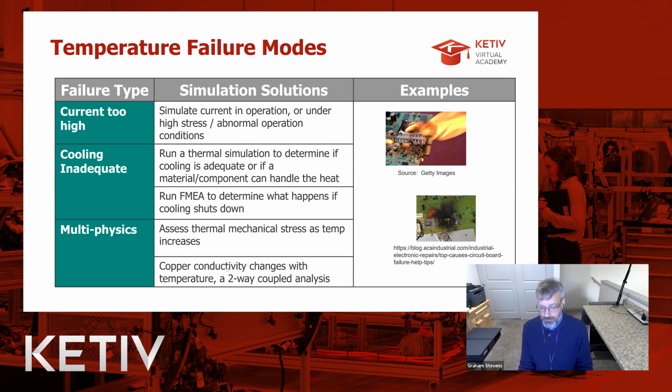And then there may also be some multi-physics simulations that might be useful in this situation, where thermal mechanical stress arises, or your temperature regime is so high that the conductivity of copper changes, which then changes Joule heating, which then changes your stress, your thermal stress, and you might need a two-way coupled analysis. So these are just some of the different types of simulations you might run in terms of testing whether your design is going to work thermally.